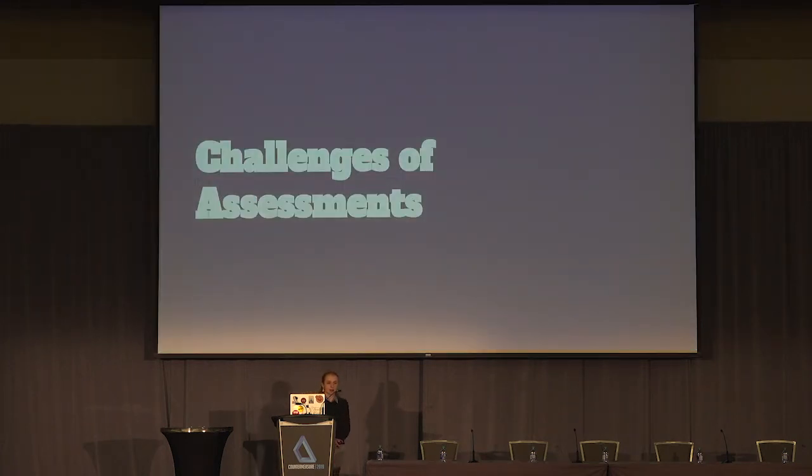All right, so how do we defend against this, though, right? We have all these different types of hardware implants. We want to look at the board and say, this is perfectly good or not. Now, one thing that people are playing with is, before fab time, the actual RTL, or the silicon design of the chip, can be formally verified. Companies like Galois are creating tooling to allow you to say, this circuit design is 100% secure, or this circuit does exactly this. Nothing more, nothing less. And that's one way to lock down the silicon of the chip.